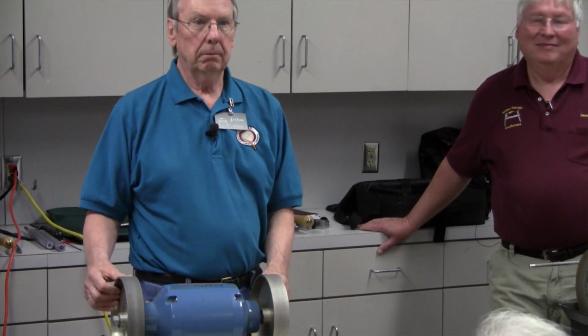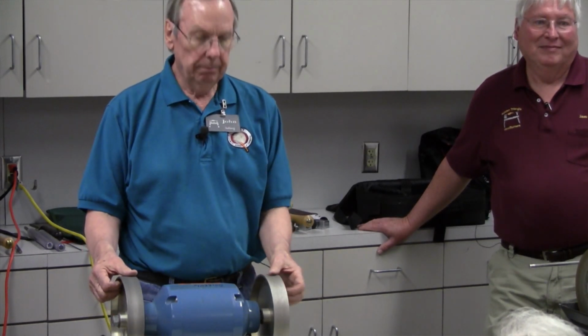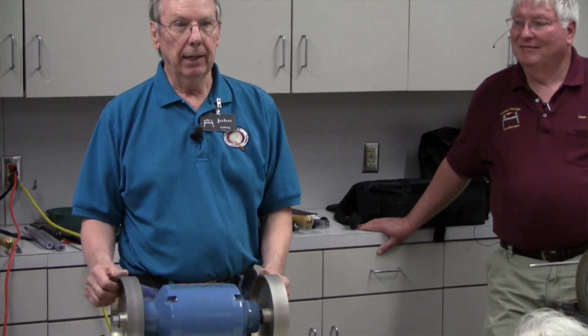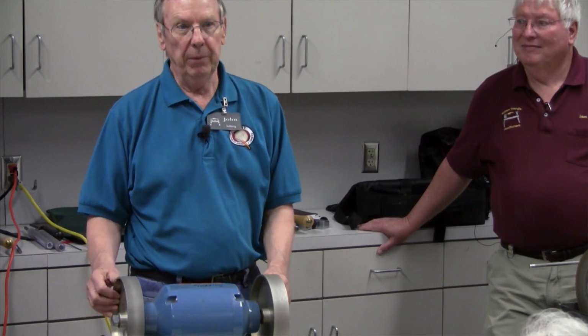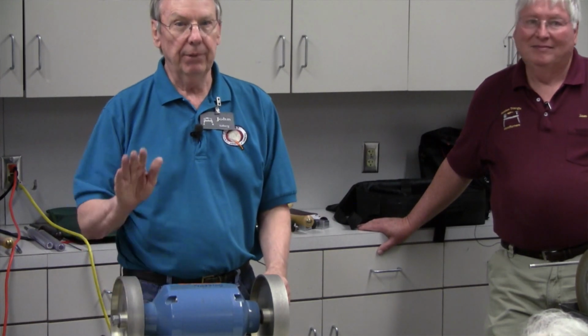Wheel, you'll use a CBN wheel for heavy hauling? Yeah, I use the CBN 80 grit wheel to do most of the grinding if I want to reshape something or make a tool. And then I'll finish it on the 180 grit to give me the fine edge.